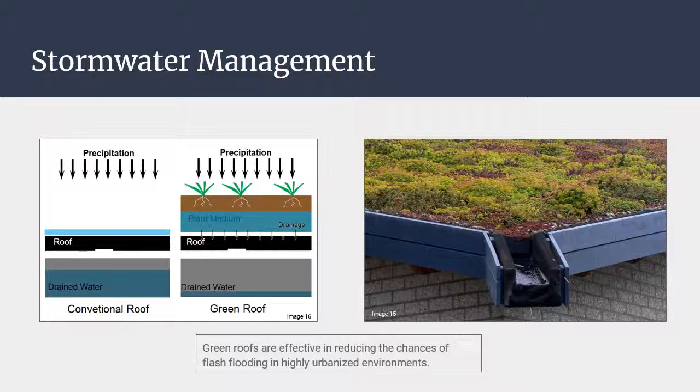Average runoff retention of green roofs ranges from between 10% and 60%, depending on the magnitude and length of rain events. Green roof systems manage stormwater before it drains off the roof, addressing the stormwater issue at the source rather than after the runoff has been collected.